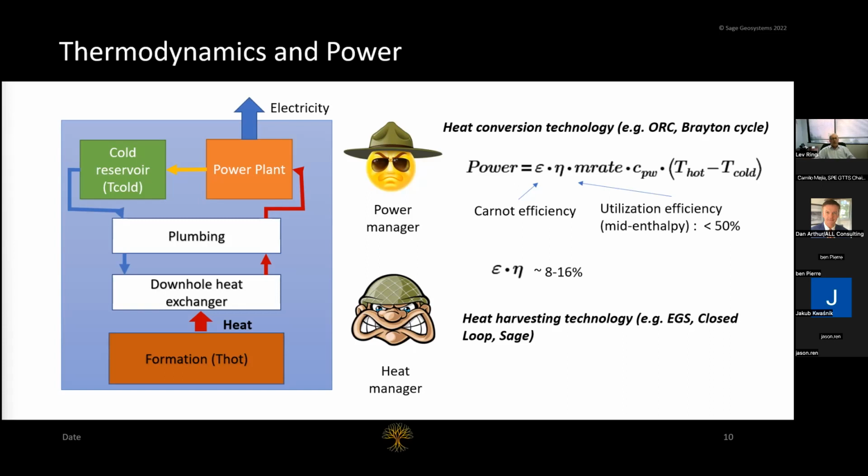Whatever it is, the only thing you need is a flow meter and temperature gauge, okay? You need to measure mass flow rate, and you need to know the temperature that working fluid is coming at you, and then you want to cool it as low as possible and re-inject, okay?